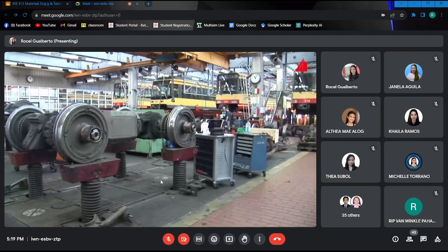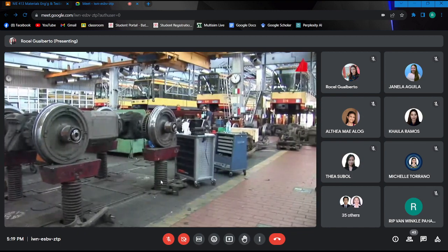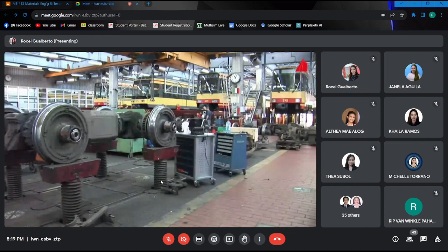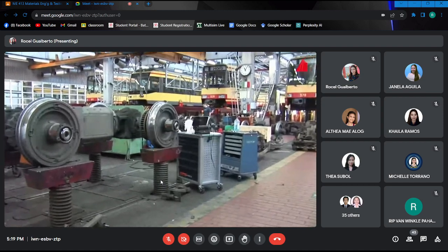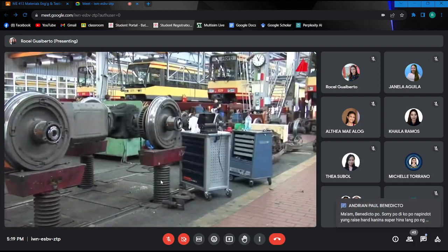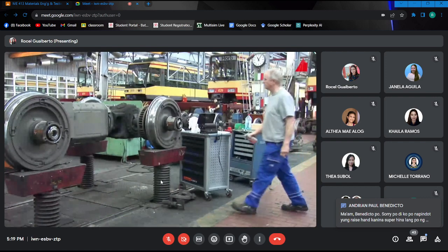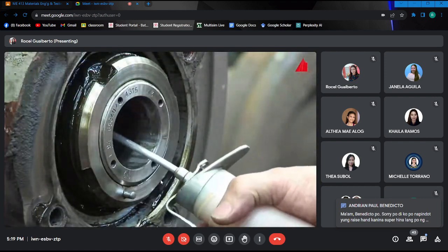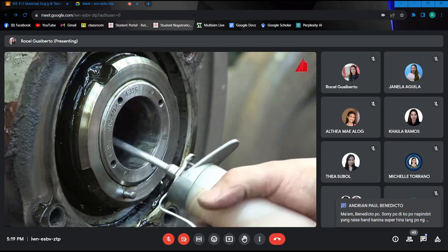Special attention is given to the wheel axle, among experts known as wheel set axle. It has been designed as a hollow axle. This saves weight and facilitates the ultrasonic examination. The material tester applies a suitable oil as a couplant into the bore of the axle.